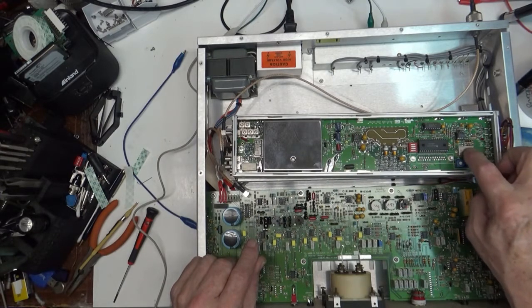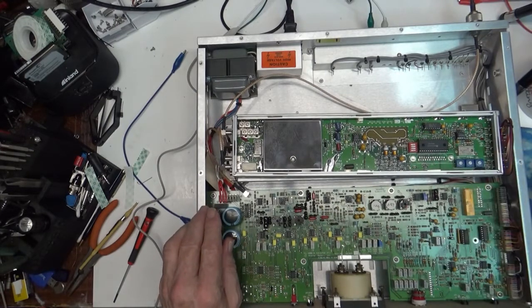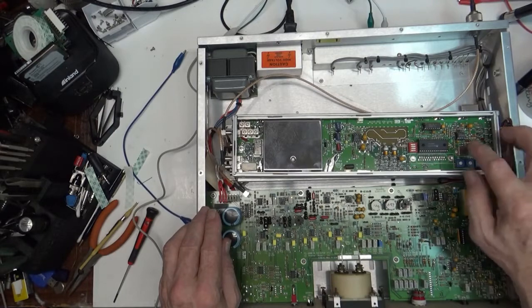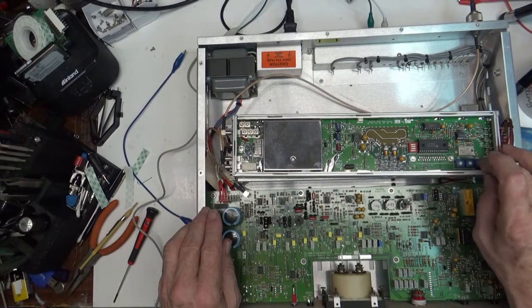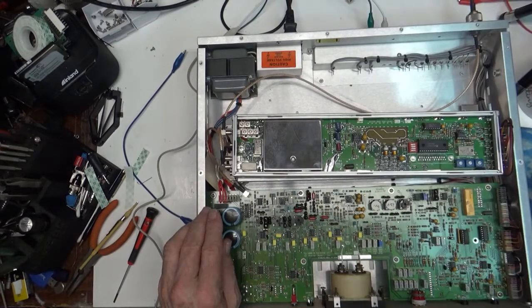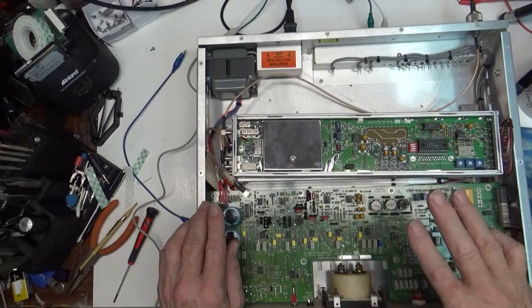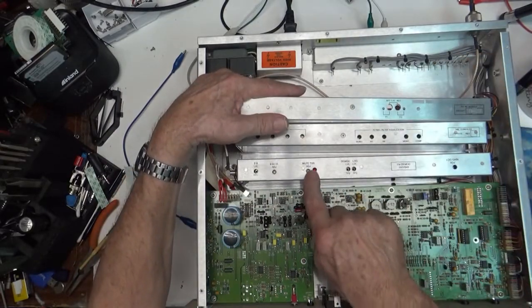This one you don't have to diddle with the frequency because it is much more accurate than the transmitter is because of this TCXO. And just make sure that you're good on here. Check your mux levels in, check your RF in, and set it for about 20 microvolts mute adjust right here.